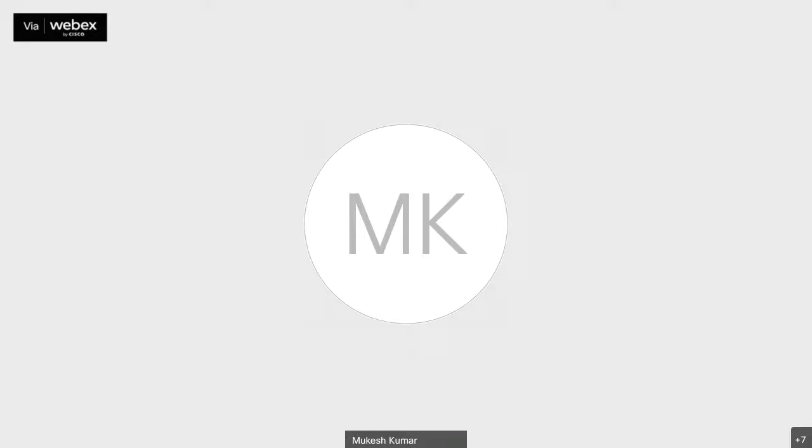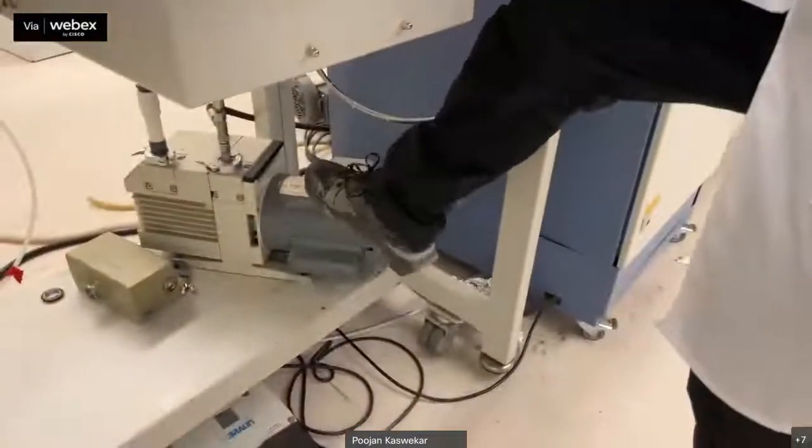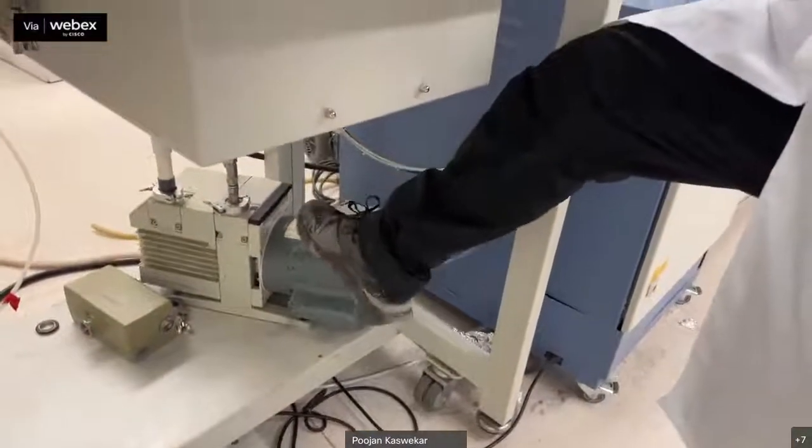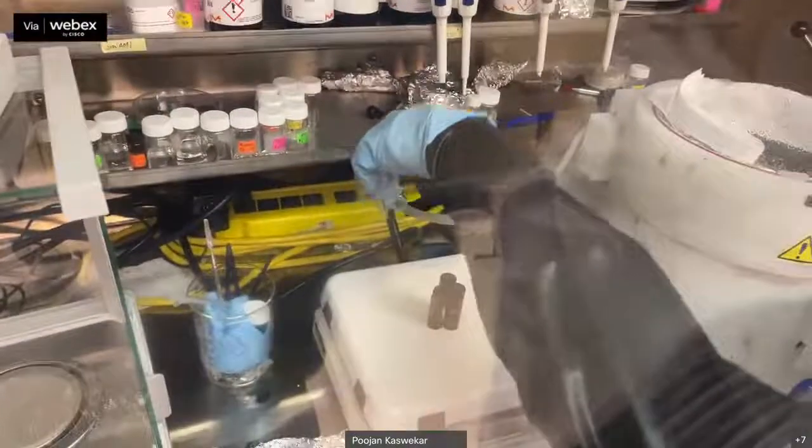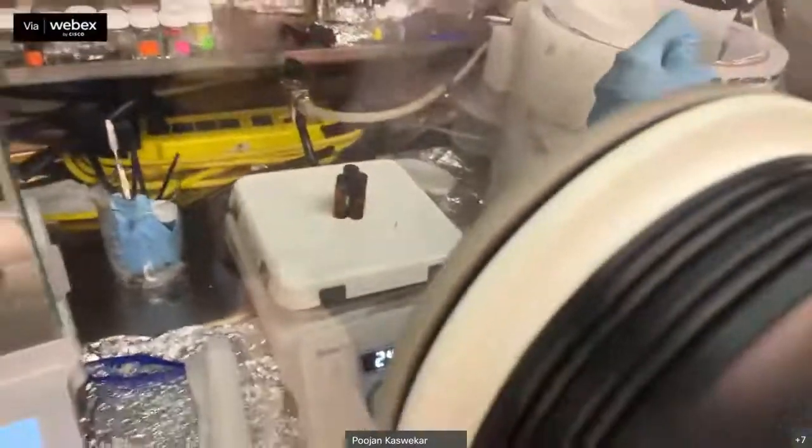So now we can turn on the motor. And turn on the vacuum. So always turn on the motor first and turn on the vacuum later. Since if you do it reversely, the pressure will be affected.